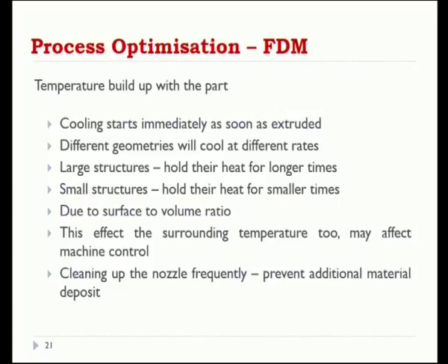Mostly, for all of these, the major factor is the input. Once we have the proper temperature and proper pressure input, we can eliminate most of these problems. So that's how we need to optimize, always based on the input temperature and input pressure, which indirectly controls the temperature within the chamber. Again, say the material is laid up with different surface areas. Consider a huge ball: it has a very small, thin surface area at the bottom, a huge one in the middle, and again a thin one at the top, right?